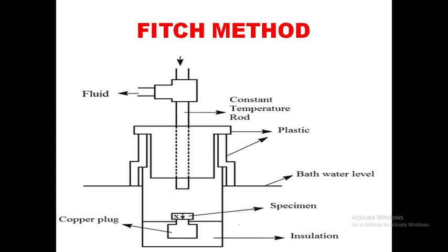The sample is firstly in thermal equilibrium with the copper block. This is shown in the figure. Refer to this diagram. The vessel is brought into contact with the specimen under a temperature differential. The temperature history of the copper block and the temperature of the bottom of the vessel are measured by thermocouples. It is assumed to have a uniform temperature distribution. Change of time and temperature are measured.